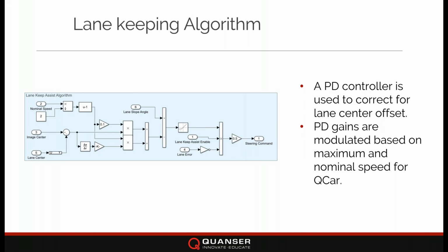I can correct a little bit more, or I can look at the deviation on my lanes and consider that more of a correcting term for where my lanes are actually sloped. The slower I'm going, that is. Whereas the faster I'm going, I may just want to consider more the slope of the lane, because that may not change as much compared to how offset I am on the lane itself. And so this was all found through experimentation.